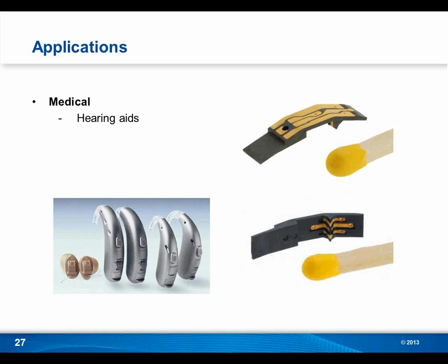And I think one of the other things that shows up in this part that's a good point is that this part has molded through-hole vias in it, and those vias are then activated with the laser and plated through, so you get front-to-back connection.